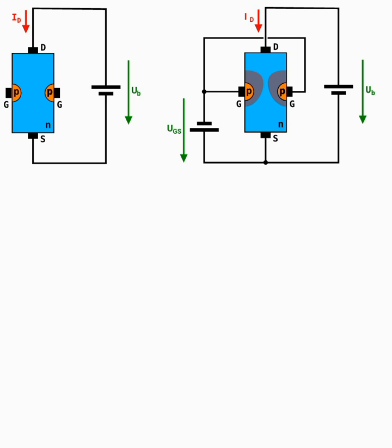Remember, because of the formation of the two PN junctions as shown in the figure, there will be depletion regions in the channel of the field effect transistor. This blue region is called the channel of the transistor. And when you have a picture as shown, where N-type material is there and the current flows through that, it is called an N channel FET.